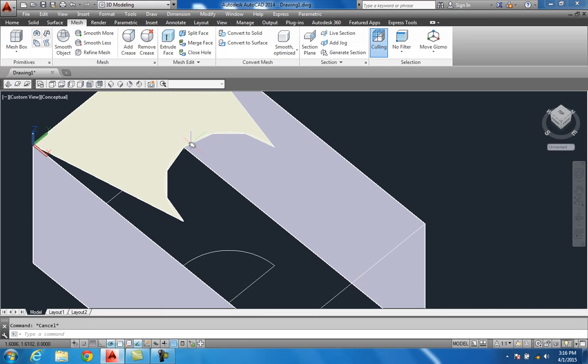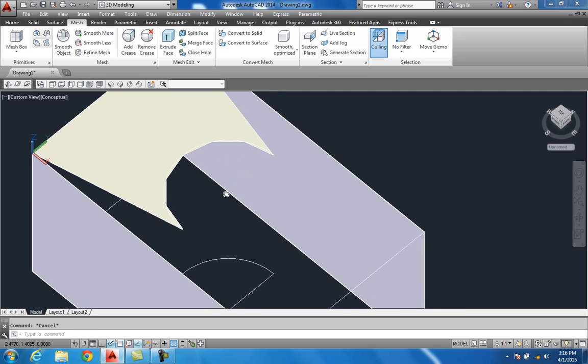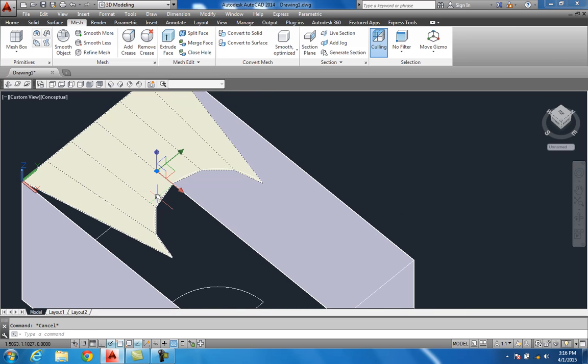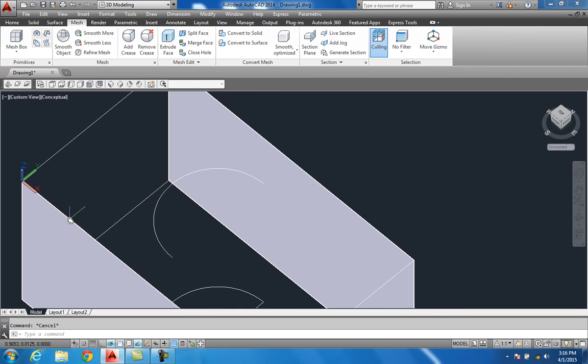You see how this is really coarse? You can set that with this. I'm going to delete that out. It's called Surf Tab 1. Enter. And you see this, it's going to have six lines. Earlier, remember it was real choppy, it just had 6 divisions going around this. The more you add, the smoother it's going to be. I can go 20 times, and check this out.